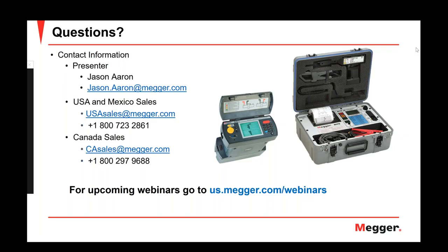So what you will do is you will do diagonal measurements, and the IEEE guide has a section which deals with exactly this situation, how to do multiple strap measurements. So it has diagrams, and you can look at that guide and see the diagrams, and that shows you clearly how the connections or the measurements need to be done on multiple straps. It's done diagonally to make sure that you get consistent values for different combinations, and also you cover all the individual posts. So that's the way you would work with a BITE 3.